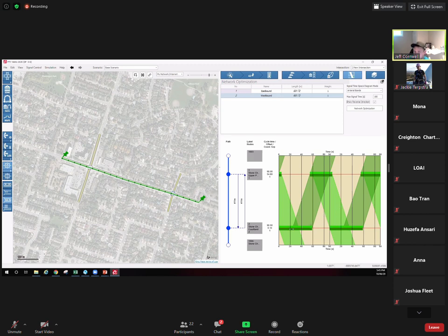When the vehicle leaves Stone Church at Cortland, if it goes near the end of the green time, it's going to get right through Stone Church Upper Paradise. And at Stone Church Upper Paradise, if it goes through just after the beginning of green, it's going to get through Stone Church at Cortland. So you can kind of see how adjusting that, you can play around with it.